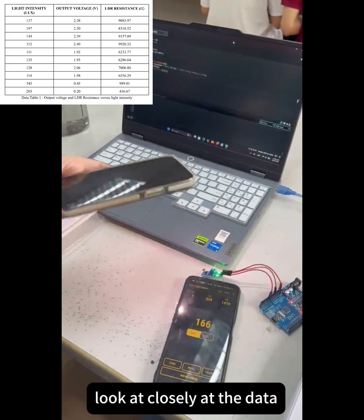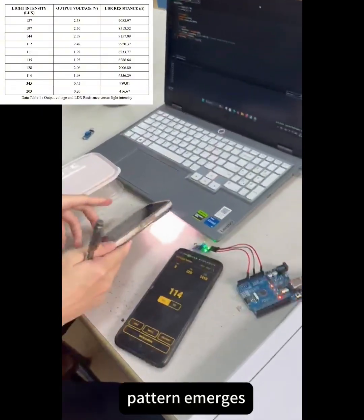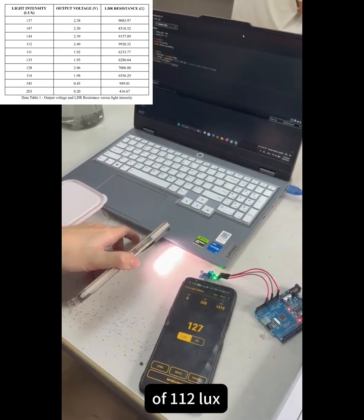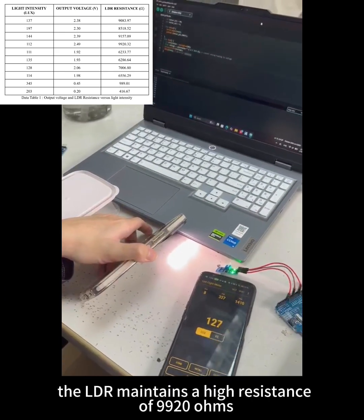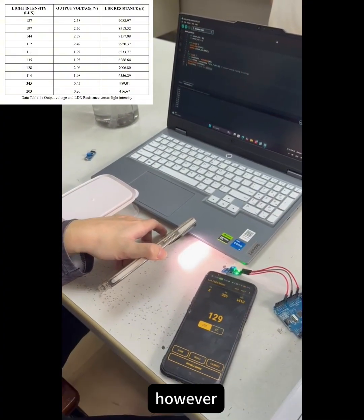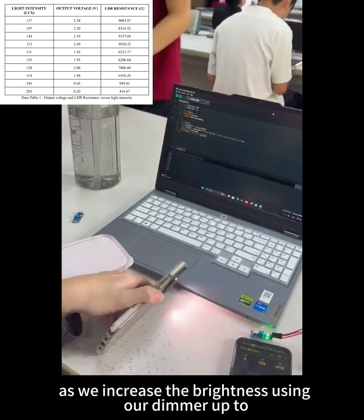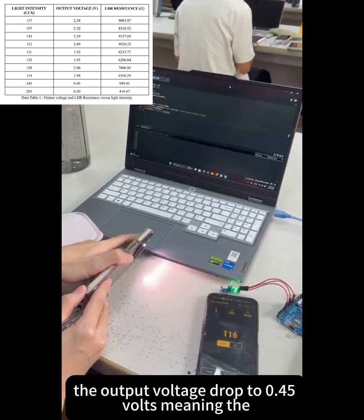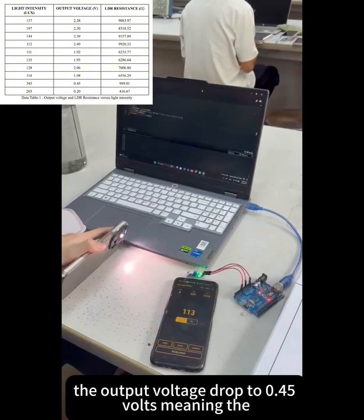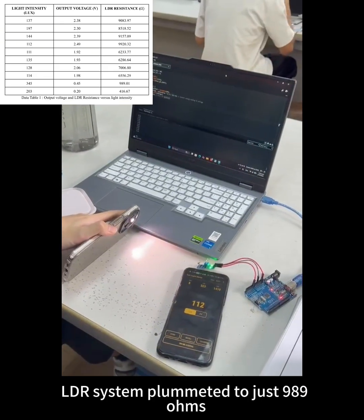Look closely at the data. A clear physical pattern emerged. At a lower light level of 112 lux, the LDR maintains a high resistance of 992 ohms. However, as we increase the brightness using our dimmer up to 345 lux, the output voltage dropped to 0.45 volts, meaning the LDR resistance plummeted to just 9 ohms.